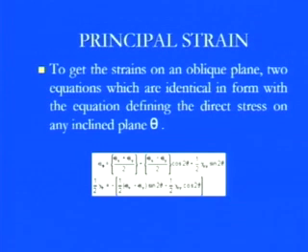First, to define those things, there are some technical terms with general definitions. We would like to first concentrate on those, and then we will go for the Mohr strain circle. First of all, the principal strain: the principal stresses were calculated just by keeping the shear stress component 0. Again we would like to calculate the principal strain, looking at what exactly the impact of the two mutually perpendicular stresses with the shear stress component is.